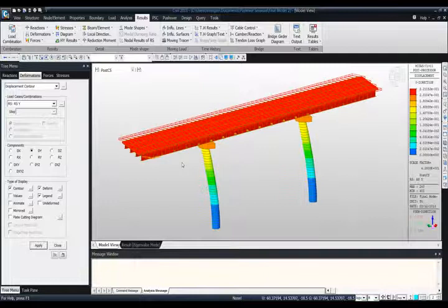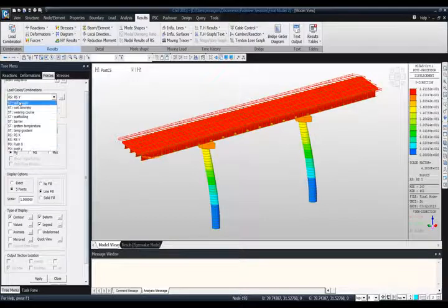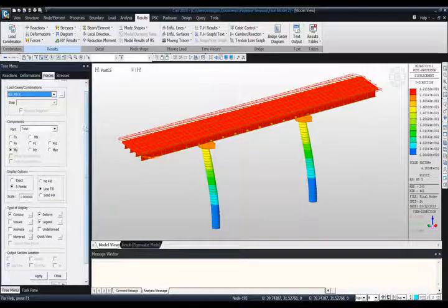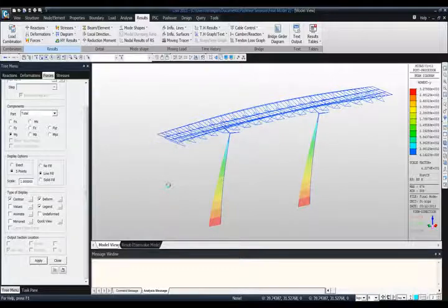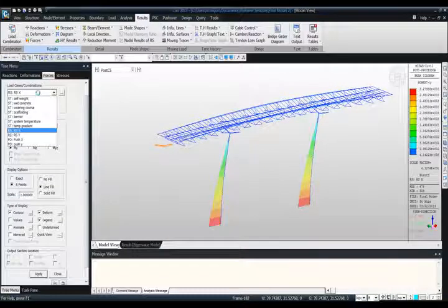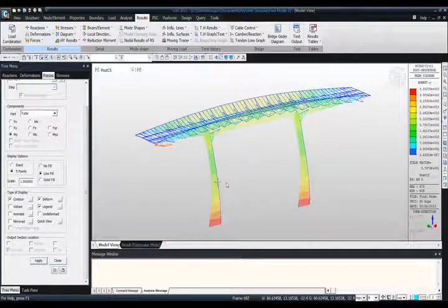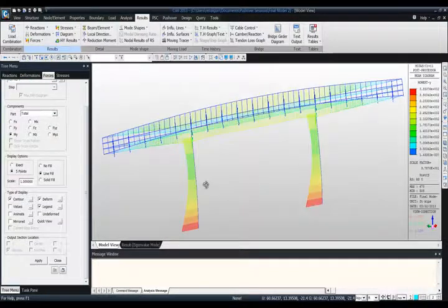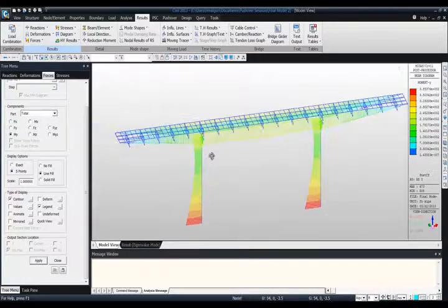You can also obtain several forces if you want to obtain the bending moment diagrams, the forces which are obtained in the different elements. You can obtain that. This is how the bending moment is obtained in the piers, in the event of earthquake in the X direction, and in the Y direction it comes out to be this. It's an exaggerated deformation, so don't worry about it, and this is how it looks like.